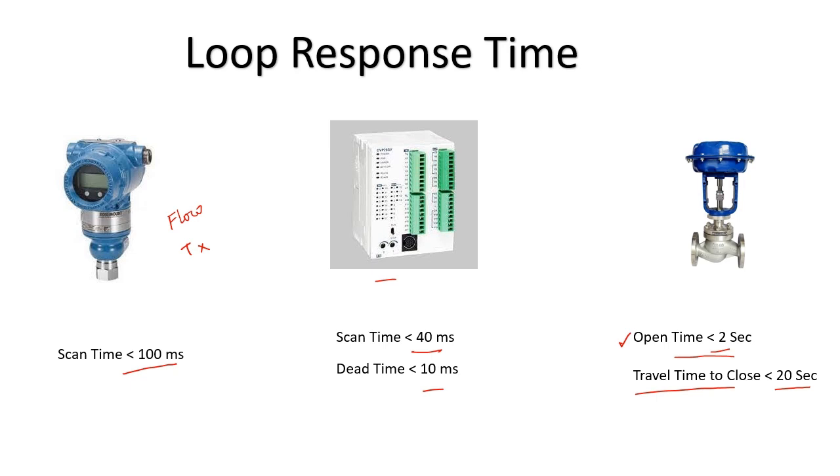Another thing to notice in this portion is the scan time of the control system. This is a control system, not an emergency shutdown system or a safety system. So one may argue, as all control systems are in the distributed control system, what is the problem of having the anti-surge control system also in the DCS? The main problem that lies here is related to the scan time.